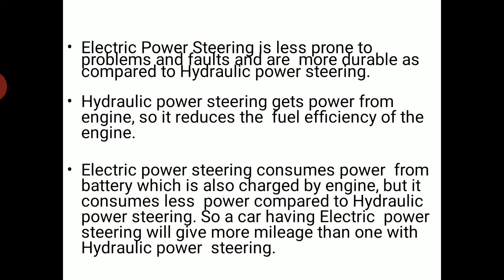From the engine only the hydraulic power is generated. Electric power steering consumes power from the battery, which is also charged by the engine, but it consumes less power compared to hydraulic power steering. So a car having electric power steering will give more mileage than one with hydraulic power steering.